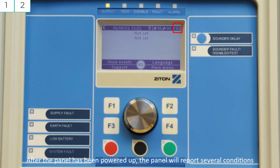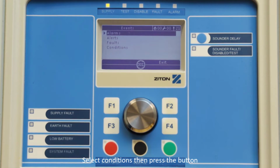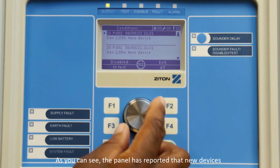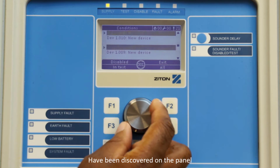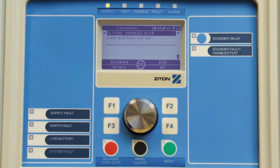After the panel has been powered up, the panel will report several conditions. You can view the conditions by pressing F1 to select Show Events. Using the jog dial button, select Conditions, then press the button. As you can see, the panel has reported that new devices have been discovered on the panel.